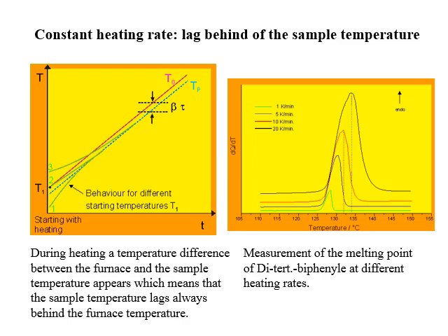On the right plot is a plot of the change in the heat as a function of the change in the temperature, plotted against the actual temperature itself. And you can see that that dQ/dt peak is much larger when the heating is the fastest, right? So you get a substantially large increase in this dQ/dt value when you heat fast.